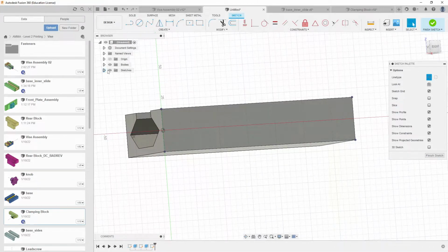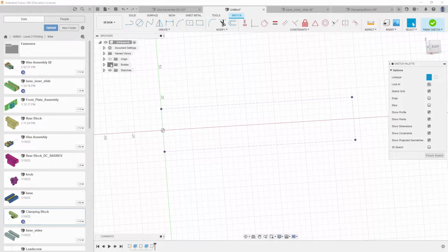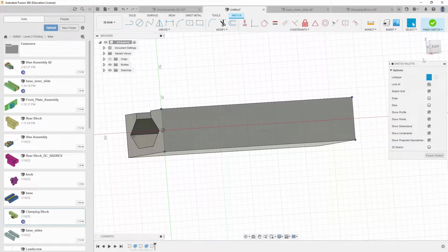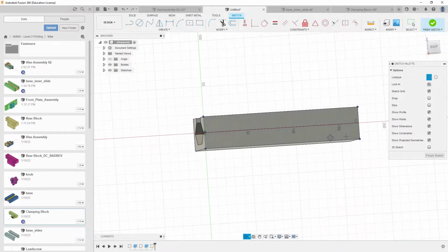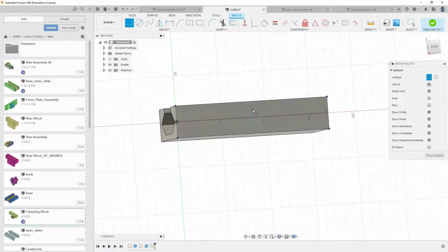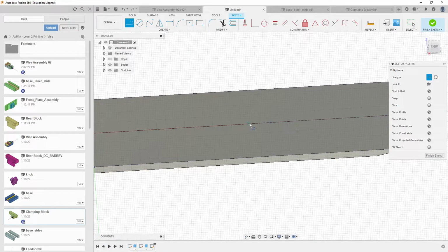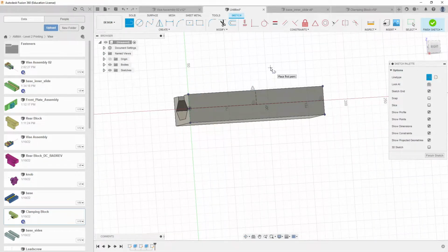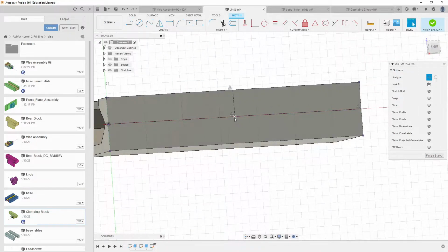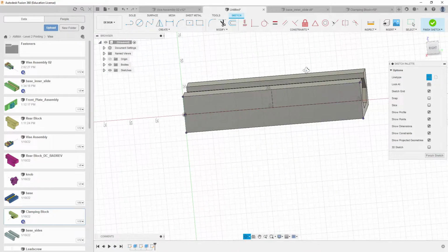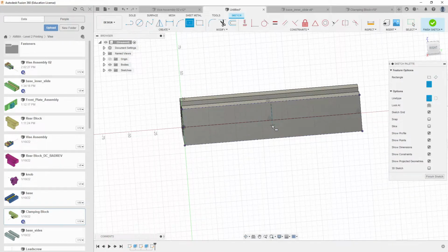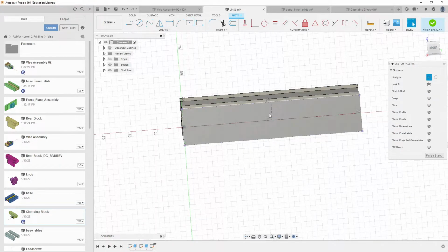Now, if I hide bodies again, they are construction elements. You see, construction elements is still on. So now I'm going to grab a line, and I'm going to go from here over to here. And that's actually pretty much sufficient unless I need a symmetry line as well. So I'll find the center line here, right there, like so, and I'll bring that up to there, possibly, just in case, right? It also gives me an actual point, even though I did have a midpoint. Now, centered rectangle, right smack there. Oops, gosh, twitched.